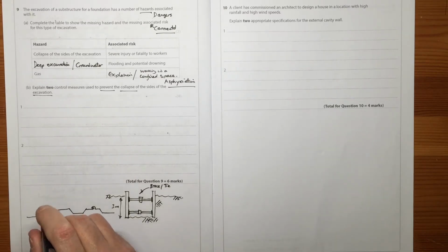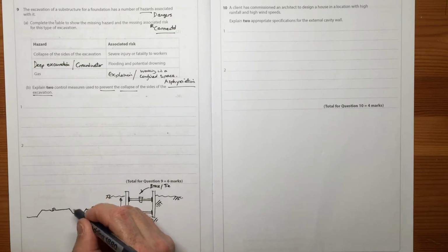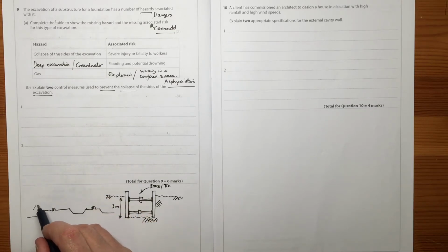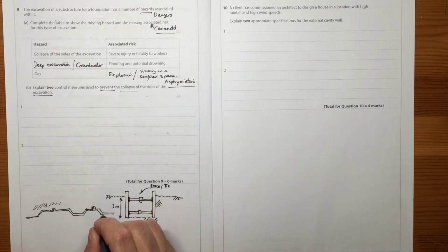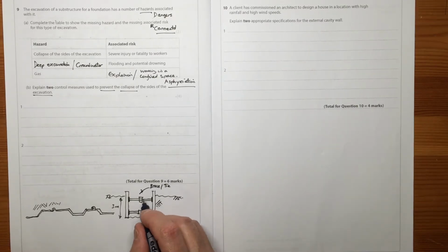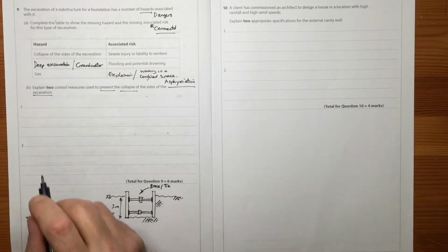So this is looking down, and you may have the sea this side and the sea wall that side, and it keeps all the earth from falling that way. Okay, sheet metal piling, secant piling. Look that up, secant piling. So these are piled into the ground, and these could be vertically 10 to 20 meters deep. Right, so this is more for the domestic trench, for perhaps a strip foundation, or even excavation for road surface repairs. So let's put that.